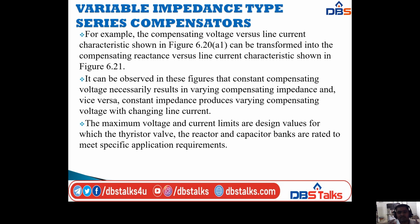So from these figures it can be observed that constant compensating voltage necessarily results in varying compensating impedance and vice versa, and constant impedance produces varying compensating voltage with changing line current. The maximum voltage and current limits are design values for which the thyristor valve, the reactor and capacitor banks are rated to meet the specific application requirements.